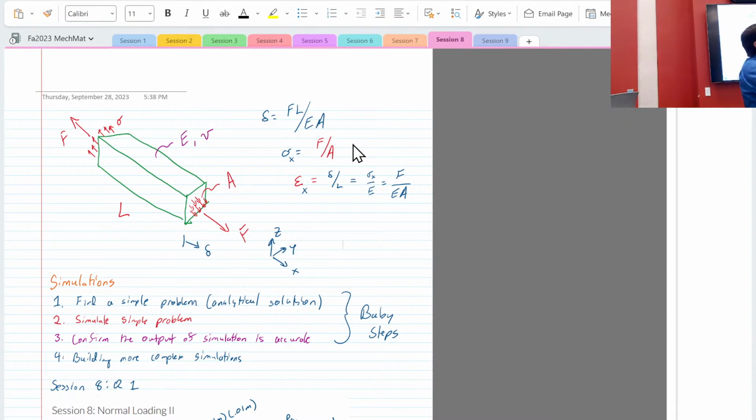Sometimes if you use the rigid body, okay, so what happens in finite element? Often we have to constrain one end at a wall, right? That's because we need to make sure all 6 degrees of freedom are not moving. Otherwise, if I apply a force, this thing's just going to accelerate. What happens though is we have an idealized situation. In this case, there's no constraint on the end. This thing is just in space. And so we've got the force over the area. We got this beautiful stress. The stress is uniform. Is that real? Well, in this fictional world, it is. In a real scenario, though, right?